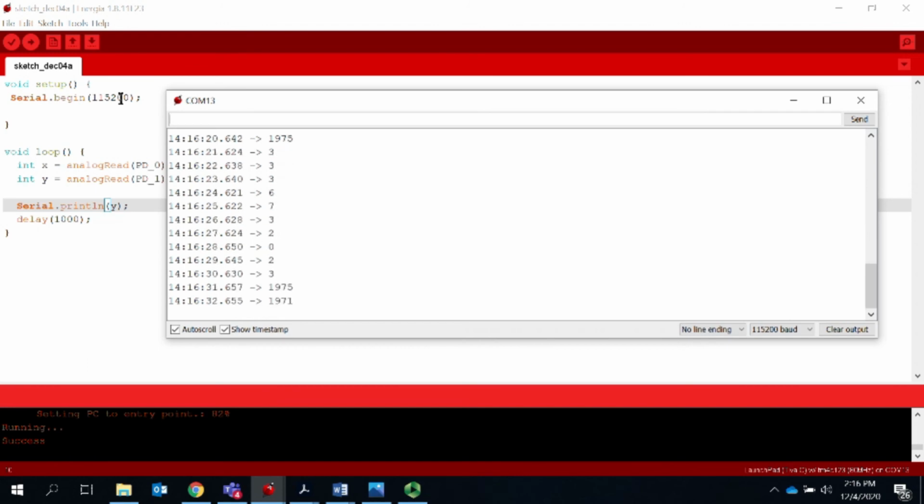If you go the opposite way and push it down, as far as you can go on the y-axis, it will give you 4093 or 4, which is close to the 4096 that we expect, okay? So pushing the joystick forward, the smallest number you could get is 6, and if you push backward on the y-axis, 4094 is what you get.